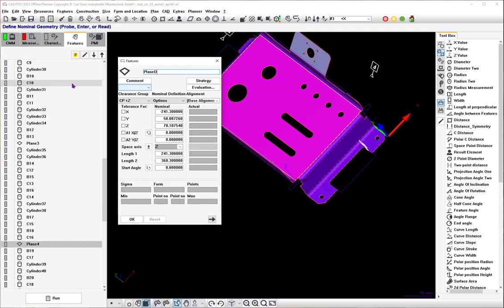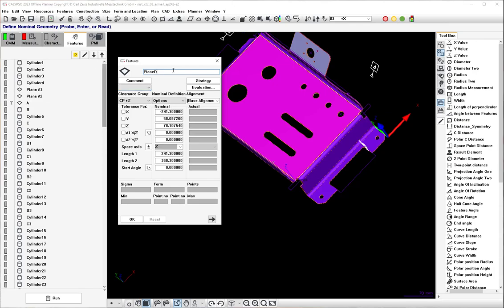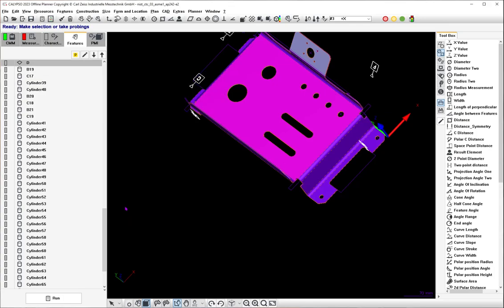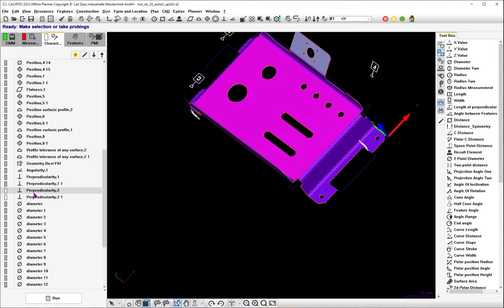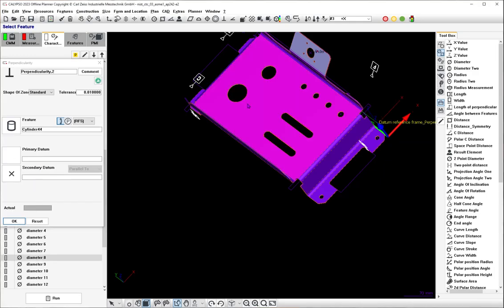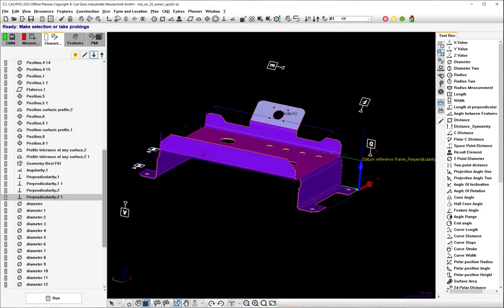It's D. What's the naming convention it wanted to use? It would have called it just D. Oof, I don't like that. I have to leave the feature name, but in the PMI, you now have a D. So that would fix these, right? So boom. It just didn't identify it properly.